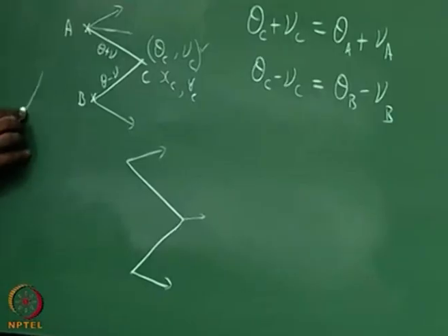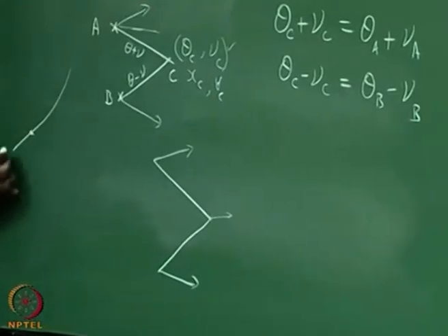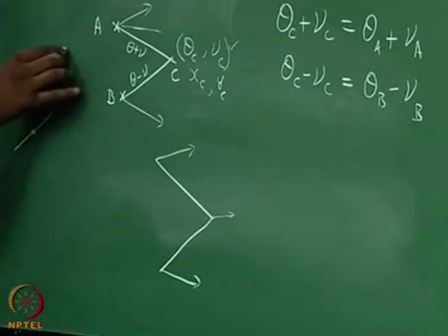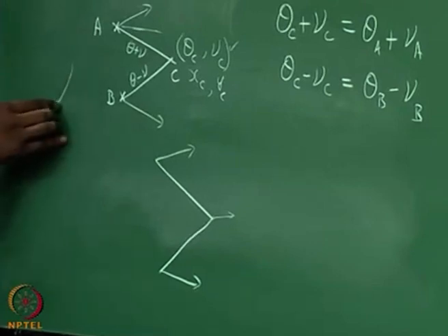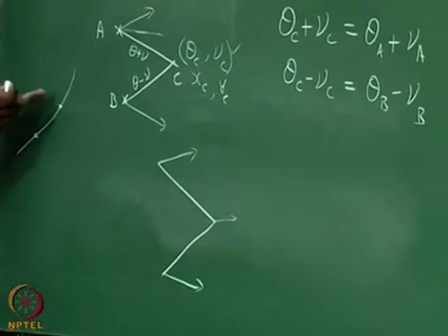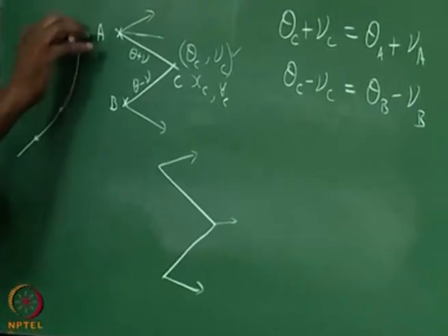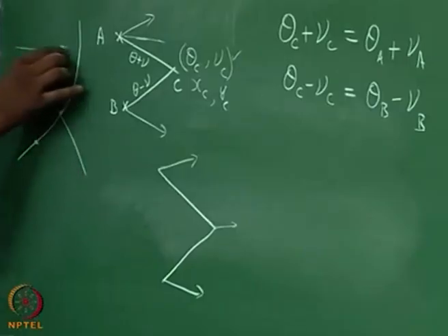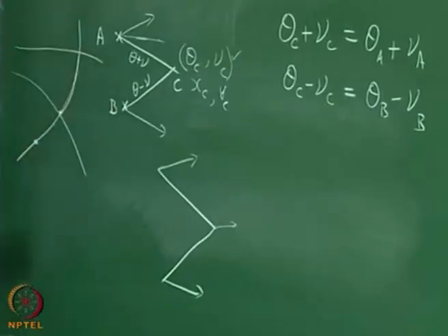Depending on the flow direction, locally that particular theta and mu, that is theta plus the Mach angle, will decide my left running characteristic. At this point, if the Mach number and theta are such that it is going to change, the characteristic may keep turning like this. Similarly, the other characteristic may turn like this, and do different things.